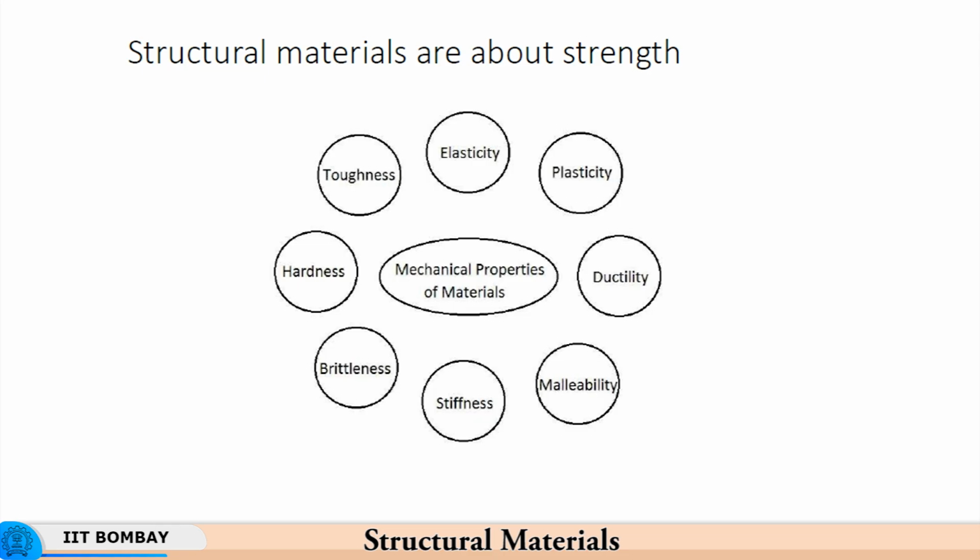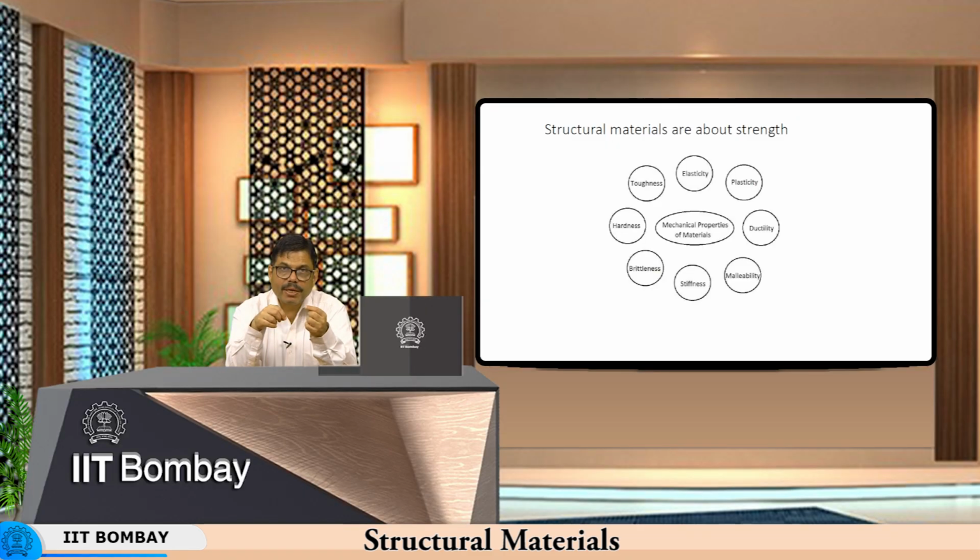When the material is brittle, as in the case of cast iron or glass, we have all experienced a glass object shattering into pieces. That is because it does not have any ductility at all. It fractures very easily. When you break glass, you make a scratch on the glass and then just bend it, and the glass breaks. A small scratch results in breakage of the glass because it has no ductility. A small strain applied to it just breaks it. This is what happens when you deal with brittle materials.